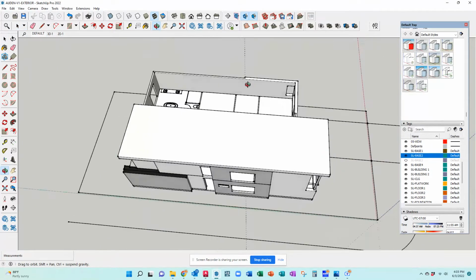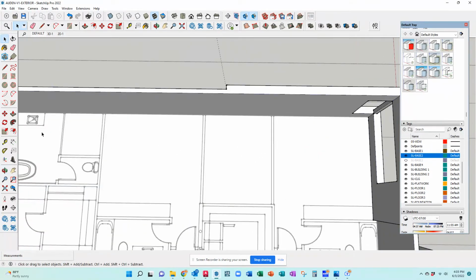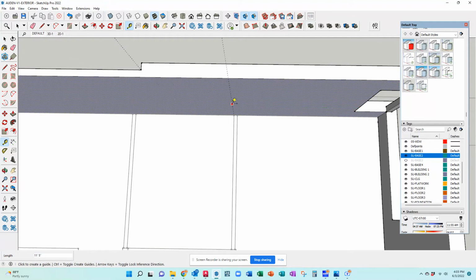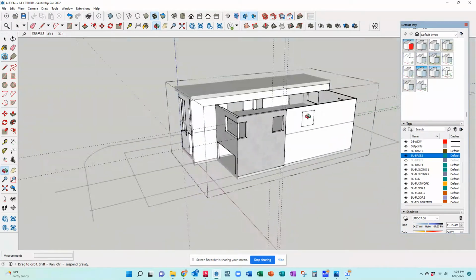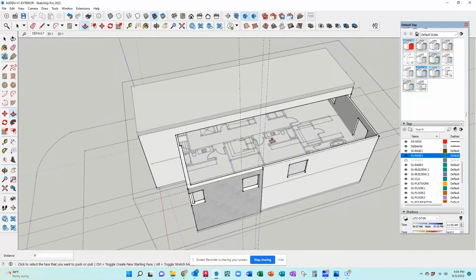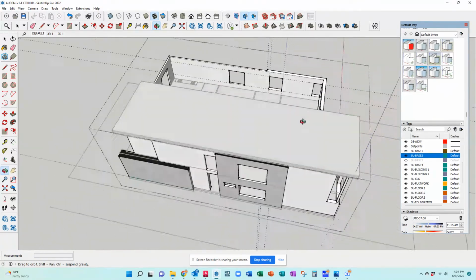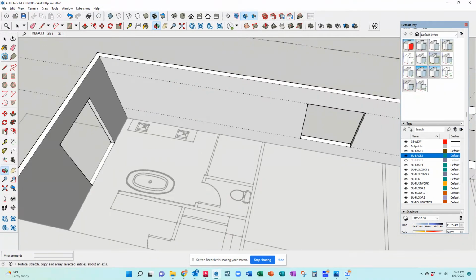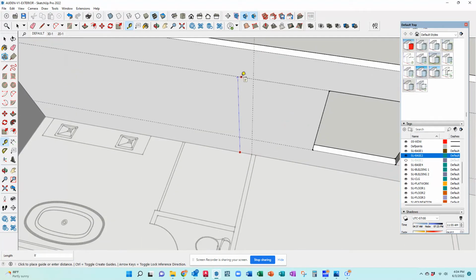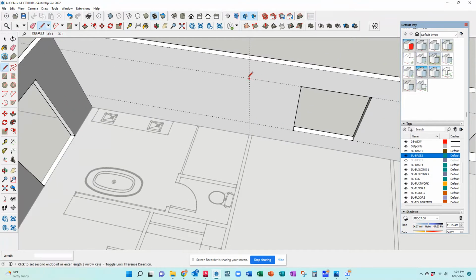So I did the 6-inch projection on the right side so that we can continue that material break down the side, do a little 6-inch wrap, and make that transition in an inside corner. It just creates cleaner massing, a more sophisticated look than a material or a color change at a simple outside corner face.